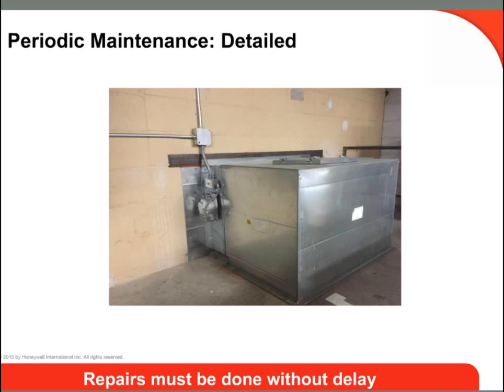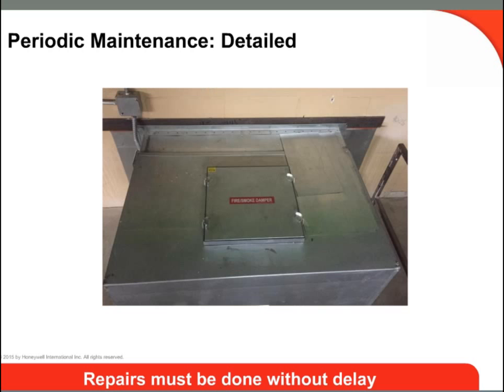During this test, verify that there is full and unobstructed access to the damper and its components, and that they are correctly labeled. In order to save time during inspection, motorized dampers can be operated remotely if the dampers are equipped with position indication such as end switches. Then the position can be monitored remotely, such as on a fire panel. However, they still do need to be physically observed for other steps of the inspection.